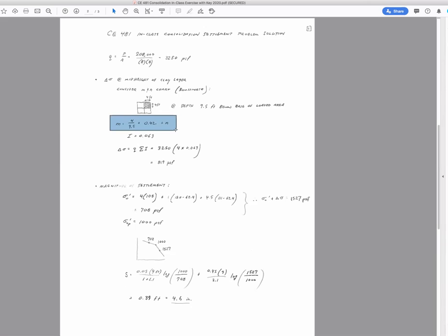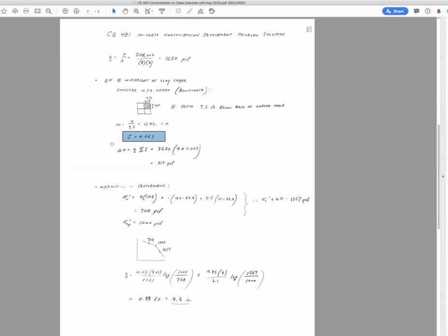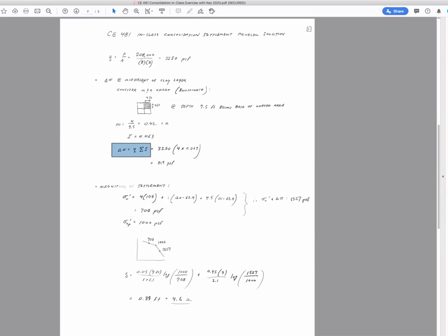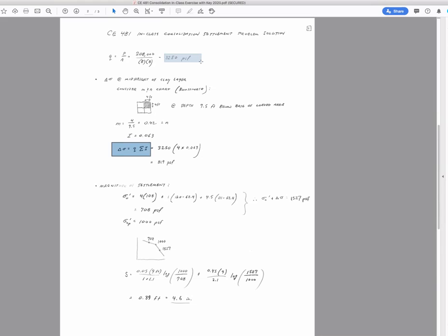And by the way, that equals N also. So B over Z and L over Z in this case are the same. I came up with an influence factor of 0.063. And the change in stress due to that loaded area is the Q value acting on that loaded area, which importantly is 3250. That's the whole amount.